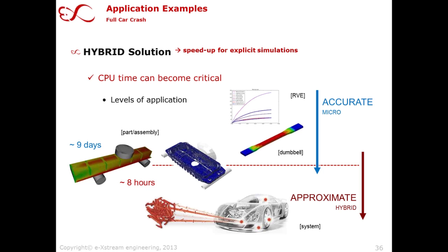And we invented that new method of describing things, basically reducing the amount of communication between Digimat and the FEA solver, performing a pre-processing of material properties and so on and so forth. So there are details to the story. But what it brought to us is it reduced our computational time from 9 days to 8 hours. And 9 days was a computation on 3 CPUs and 8 hours same on 3 CPUs.